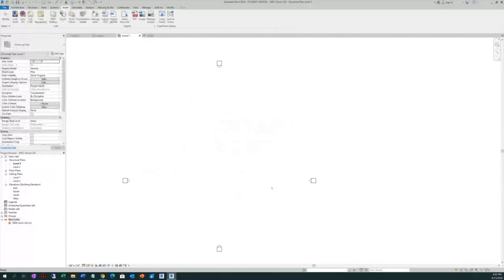Okay. So it's like in CAD at this moment, I detached the file, correct? I didn't delete it. Don't delete it. If you don't need the link file in your structural, you are going to unload it or detach it, but you don't delete it.